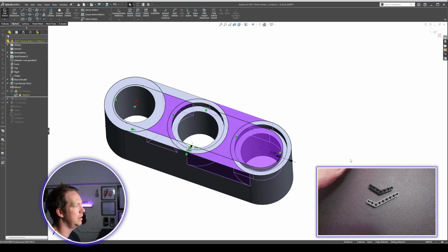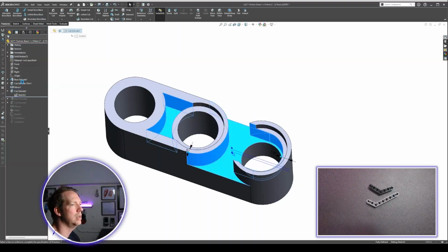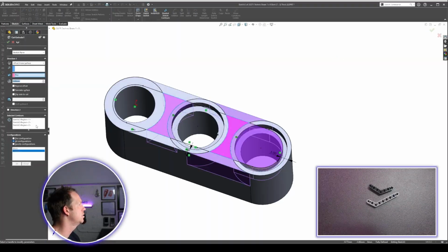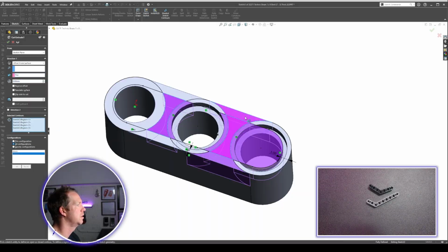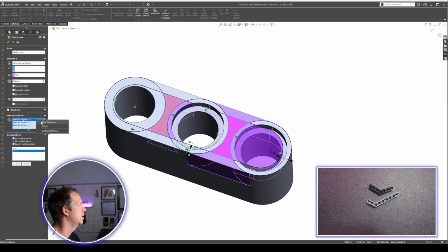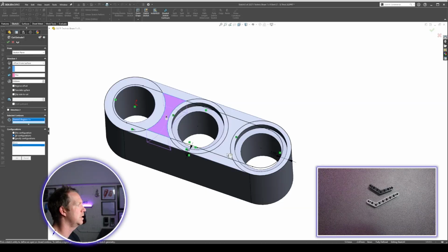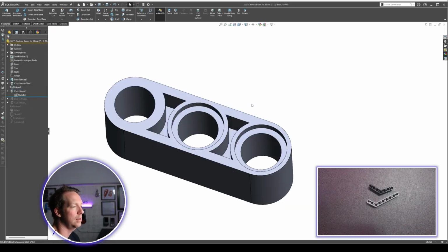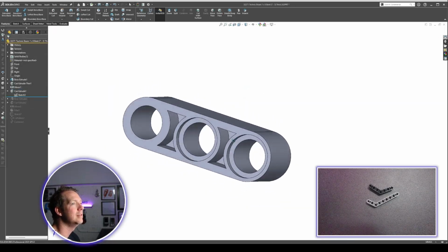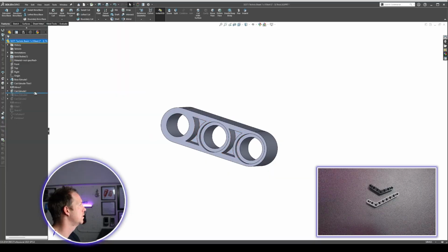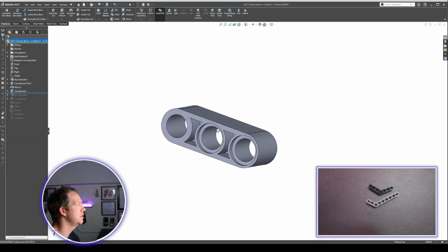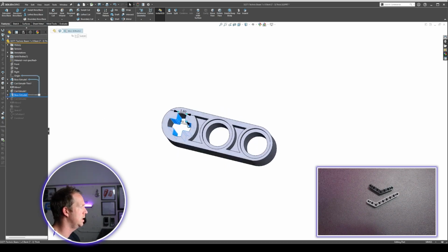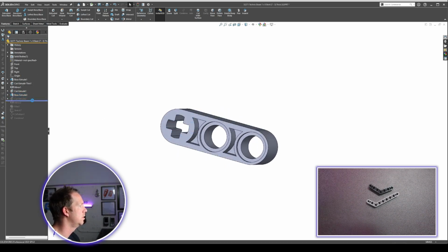I'm deleting the dangling sketch on the right-hand side, and then I'm going to exit the sketch and go into edit the feature. And all I'm doing is reselecting the contours that I'm using for the cut extrude. So I clear the contours, I select the 2 new contours that I want, accept the feature, and then the feature is updated without an error, and I've got the result that I'm after. Now this is just done on one side, but what I will do later is mirror to the other side.